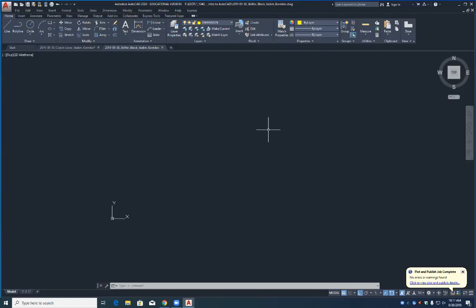If you have a problem with that, let me know and I'll work one-on-one with you to help you get that turned out. When we do a normal hidden line, how long do you think our dashes are? 1/8 of an inch. What do you think a gap is? 1/16 of an inch. Okay, now just keep that in mind. That's what a normal hidden line is.